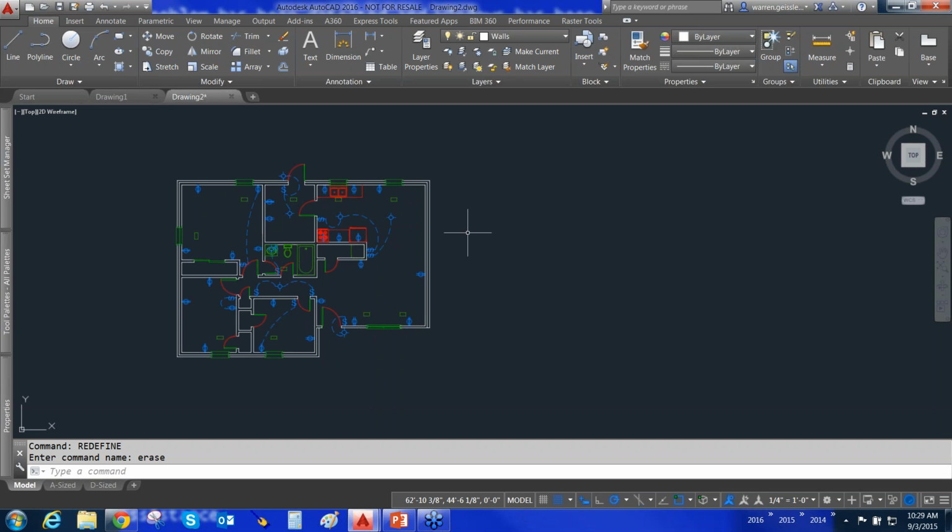In the 70s, Lisp was invented as a language, and Autodesk incorporated that as part of their programming languages. So, AutoLisp, Lisp. And I'm not going to teach you how to read Lisp or how to use a whole lot of Lisp or how to do Visual Basic or Visual Lisp or anything else like that. Lisp is just a series of commands that you can incorporate into any one of your macros or any one of your buttons, and they usually start with parentheses. So let me give you a little bit of quick Lisp in here.